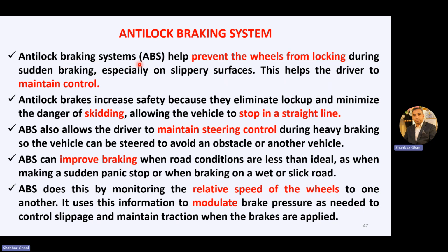So anti-lock braking system helps prevent the wheel from locking during sudden braking, especially on slippery surface. This helps the driver to maintain control. Anti-lock brakes increase safety because they eliminate lockup. Lockup means when brakes and wheels lock up, and ABS minimizes the danger of skidding.